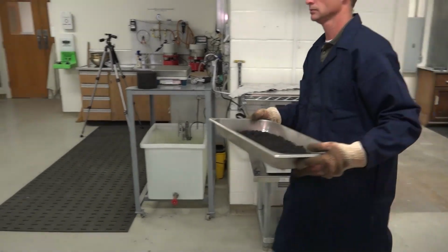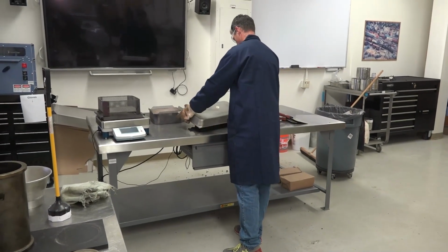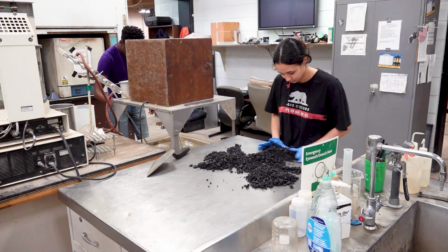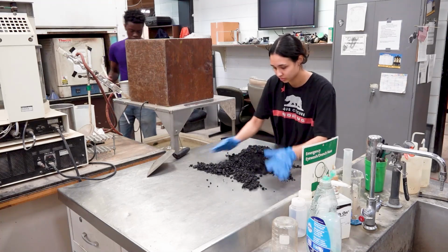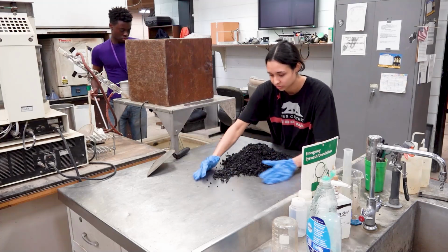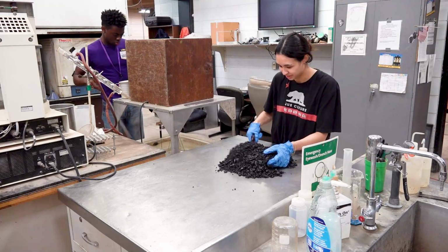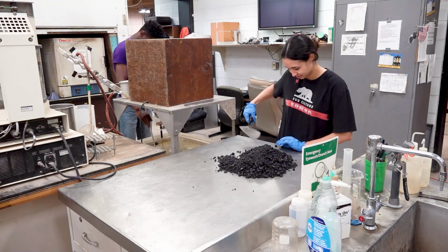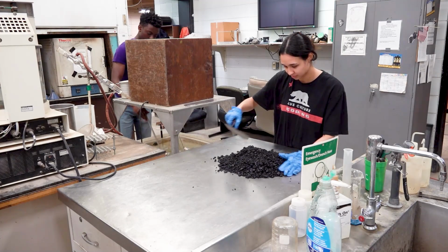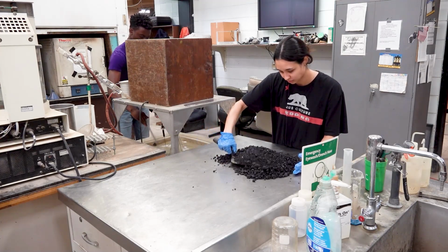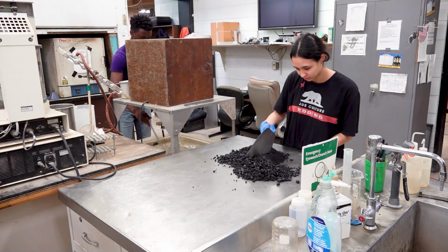Following the aging process, remove the sample from the oven and place it on a table to cool. Once cooled down enough to control by hand, gently separate the particles of the asphalt mixture, taking care to avoid fracturing the aggregate. Do this until the particles of the fine aggregate portion are no larger than 6.3 millimeters or 1/4 of an inch. Once cooled to room temperature, we are going to zero our calibrated pycnometer on the scale and then place our sample into the calibrated pycnometer.